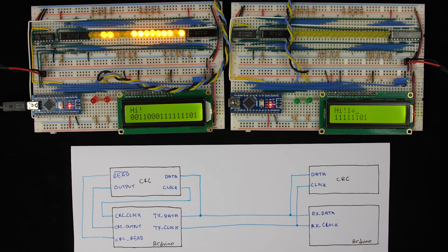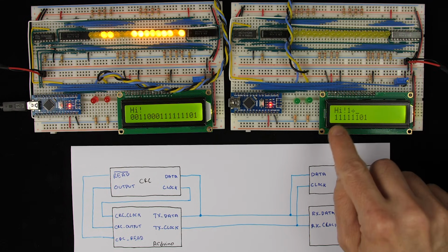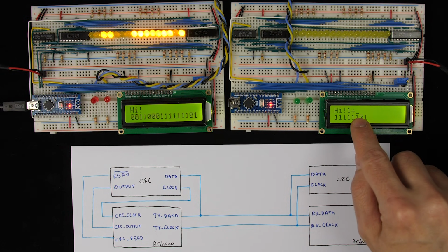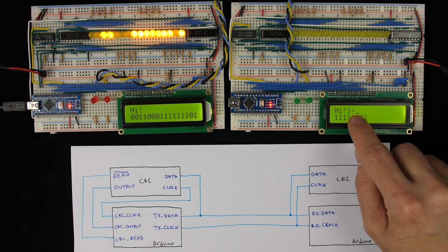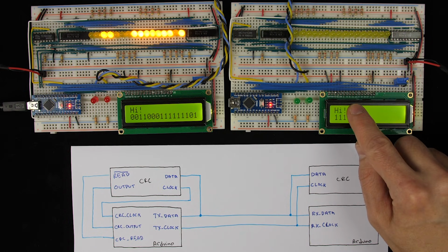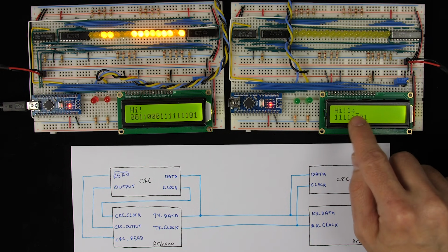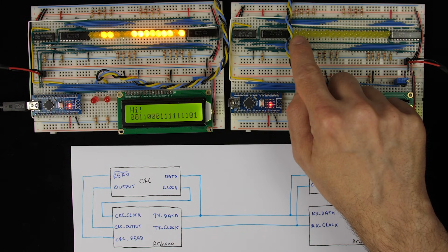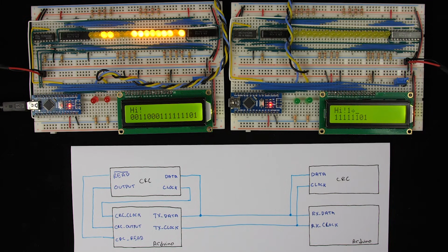That's actually how we validate that the message was received correctly, because the receiver is going to receive the message plus these 2 extra bytes, which are the 16 bits of the CRC. So this 1 and this division symbol just happens to be what our CRC works out to be. If we ignore that part, we have our message, and then we have this extra part, and when we compute the CRC of that whole thing, the CRC is 0. And that 0 validates that we received the message correctly.